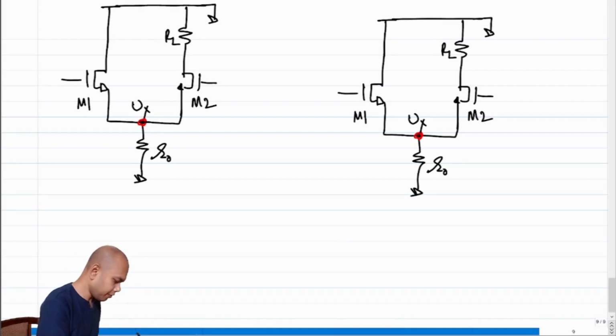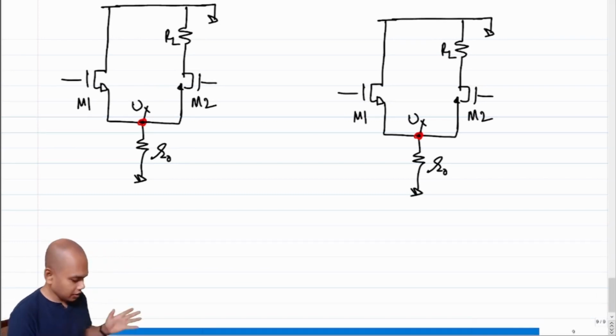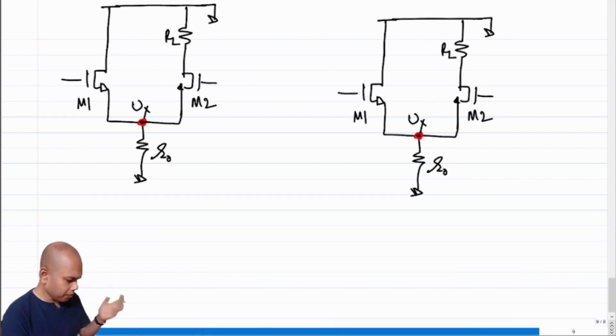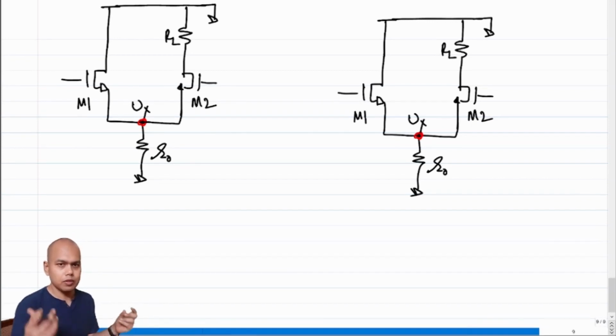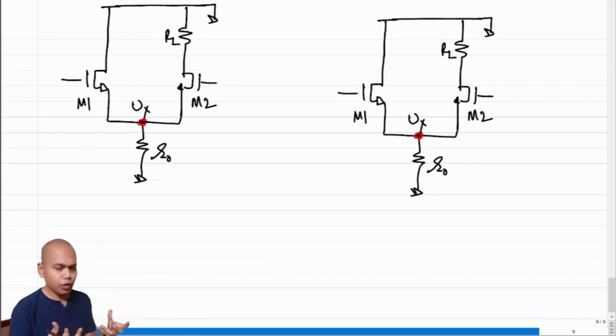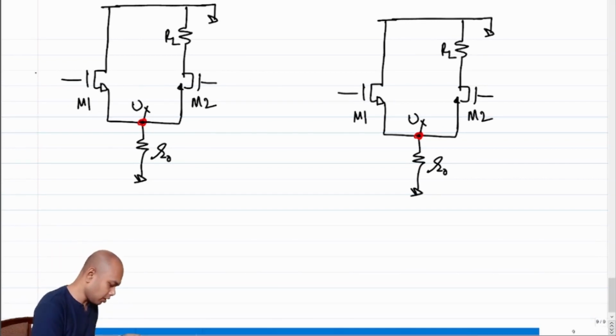So up till now we have been dealing with whatever we have been dealing with in terms of differential amplifier. We can summarize as follows. Step 1 is, we can essentially say that any arbitrary input V1 and V2 applied to the gates of M1 and M2 can be broken down into a common mode input and a differential input, and we can analyze the circuit independently of each other and add up the sums, right? So if we do that, this is what we saw.